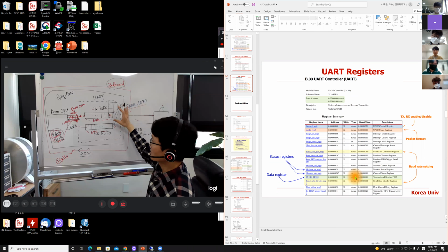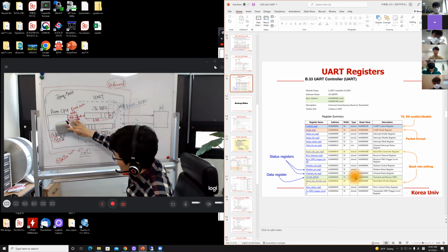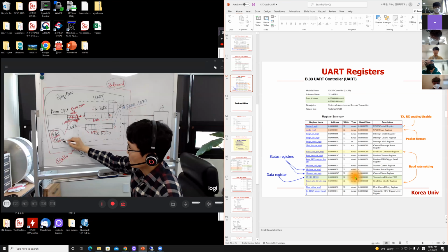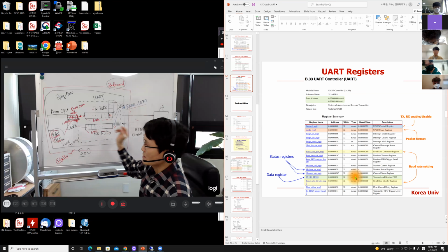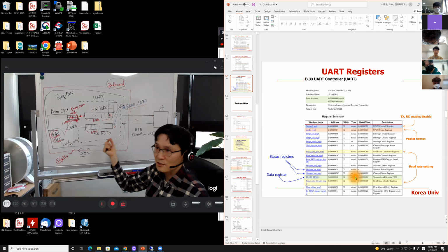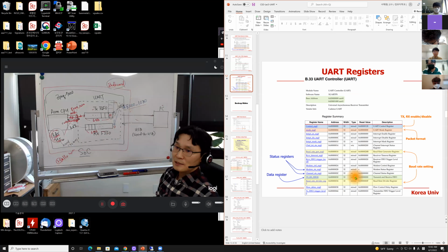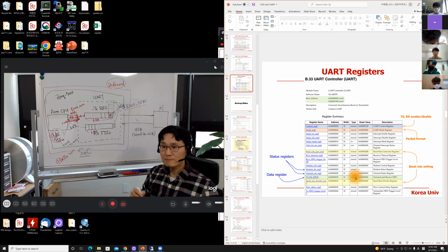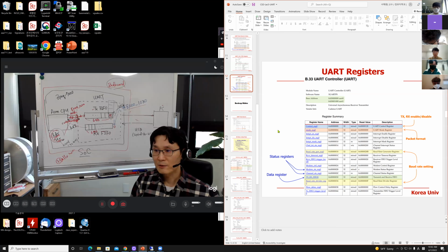But that means when you access TXRX5, you can use STR or LDR instruction, because it is a word access instruction, 32-bit data access. So it's okay to use a word access instruction, because physically you have that 4 bytes, but actually you are supposed to use this least significant byte. A little bit confusing, right, Juan?